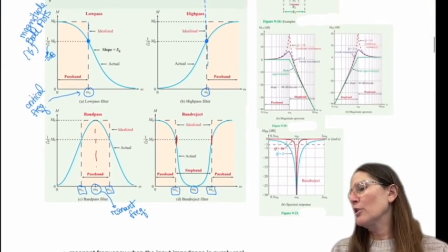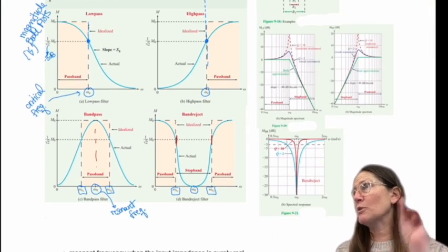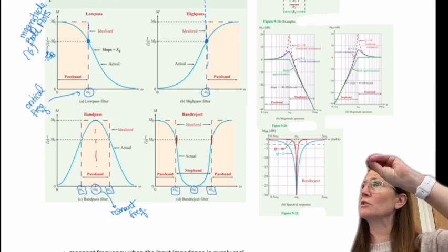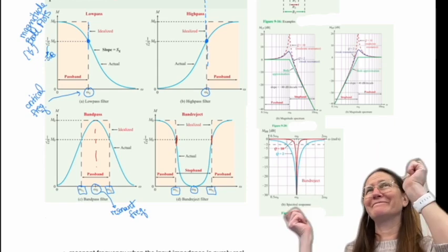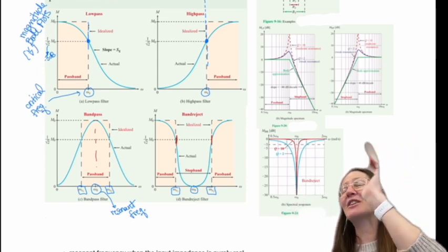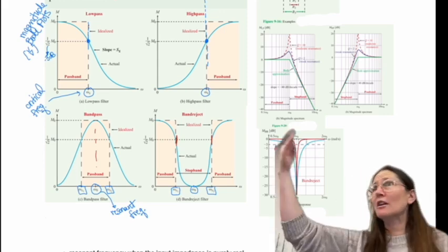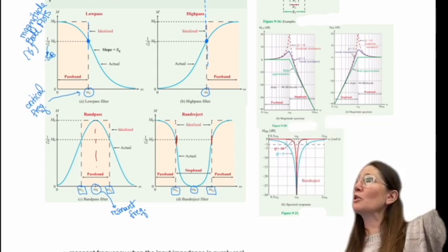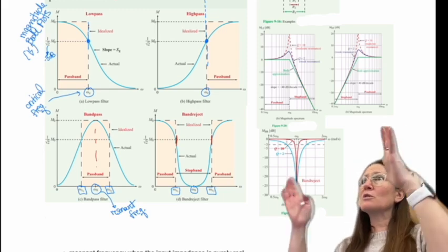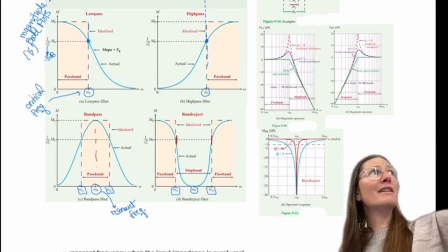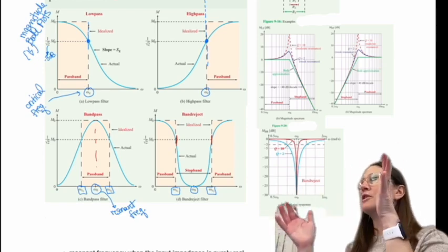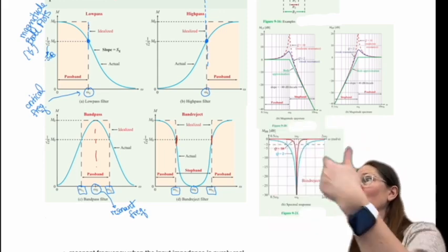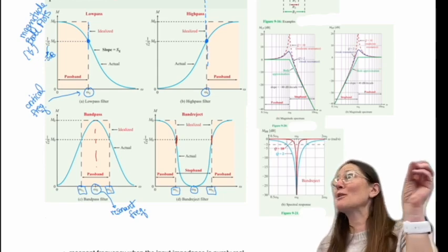Okay. So once you've graphed the magnitude plot, we can actually grab these numbers, remember, from the pole or zero locations in your, what do you call that, the transfer function. So in that transfer function, when we identify those poles and zeros, those are going to be the locations of the critical frequency for a low pass and a high pass, or it will be the regions that it's going to operate in a pass band or a band reject. So once you graph it, you can look at that graph and say, oh, that is the form of a filter, this specific filter, or it's not. So it will either be a filter or it won't be a filter.